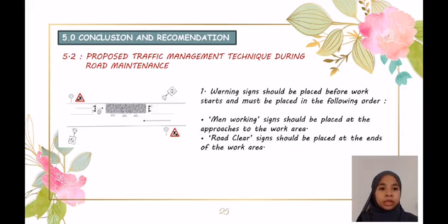Next, I will continue with the proposed traffic management technique during road maintenance. First, warning signs should be placed before work starts and must be placed in the following order. First, the man working sign should be placed at the approach to the work area, and second, the road clear sign should be placed at the end of the work area.